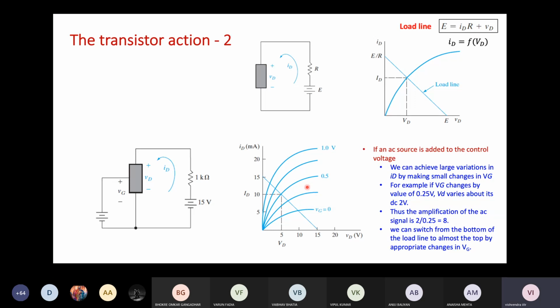But if you go back and study the MOSFETs, the P MOSFETs generally work with negative voltages, and the N MOSFETs work with positive voltages. A MOSFET is not like a simple PN junction. It is a more complicated device. We cannot say it is like a diode. There is no simple forward bias and reverse bias because there is no single junction. There are actually many junctions there.